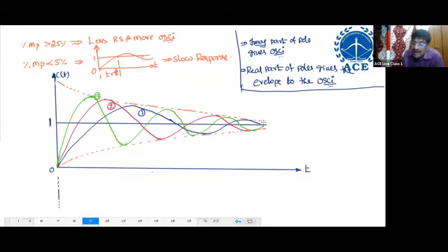Now tell, all reach the what? Same duration. Settling time is same. All reach the steady state at the same time, for example, allowable tolerance plus or minus 2%. Why is settling time the same? Because time constant is same. For all the poles, settling time is the same, and the time constant is the same. All reach the steady state at the same time.